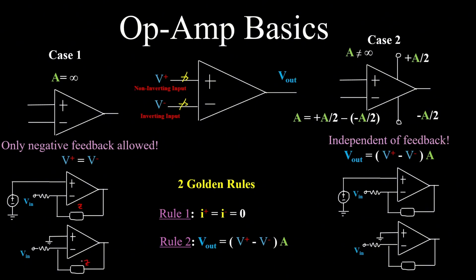Same thing with here. And this point now is going to have the same voltage as this point over here. V minus will be equal to V plus. In that case, this point will be called a virtual ground. The virtual ground has a voltage of 0 here, even though it is not actually shorted to the ground. So no current leaks to the ground over here, but this point is forced to have a voltage of 0, because this holds true.